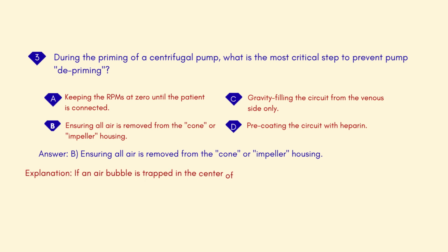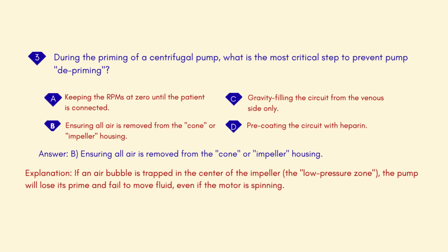Explanation: If an air bubble is trapped in the center of the impeller, the low-pressure zone, the pump will lose its prime and fail to move fluid, even if the motor is spinning.